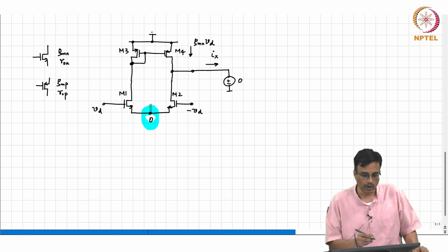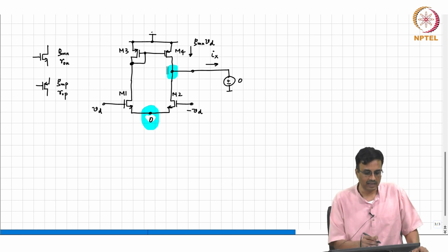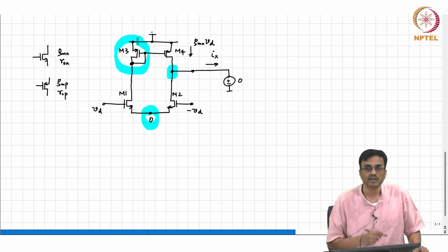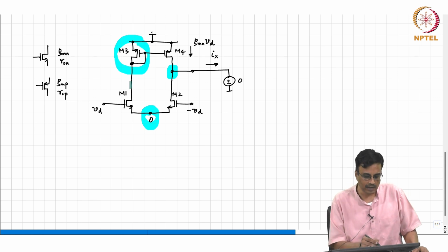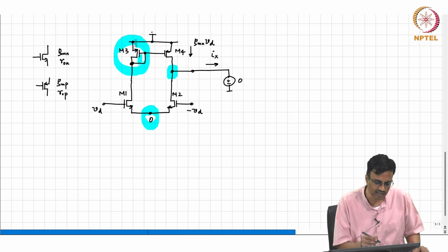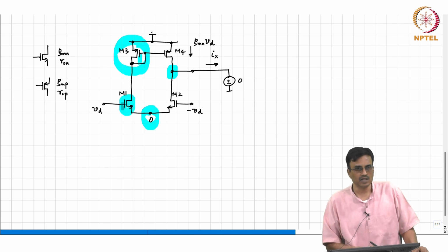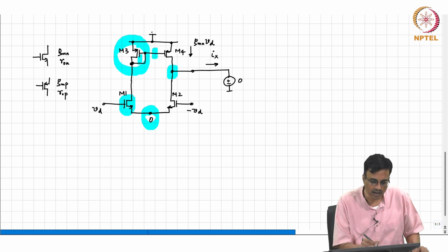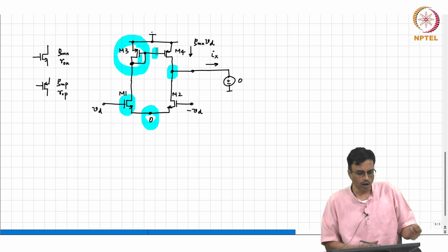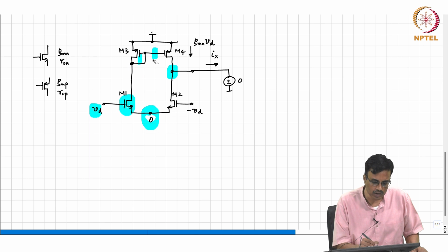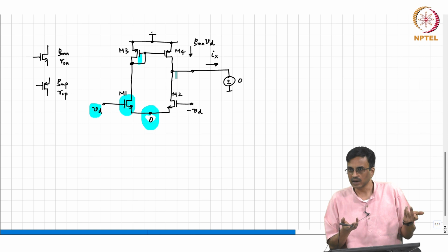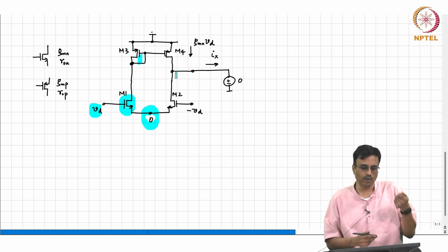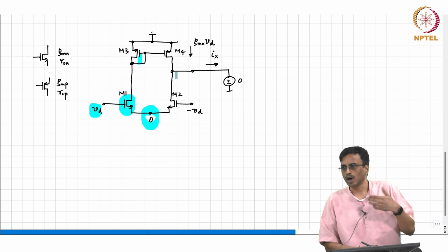However, because this is 0 and this resistance is small, or basically the resistance is of the order of the GM of the NMOS transistor, right, we see that the voltage swing here is going to be small, just like VD. Okay. So, if the drains of both M1 and M2 are pretty much not swinging, M2 of course is absolutely not swinging, M1 is swinging very little for all practical purposes.